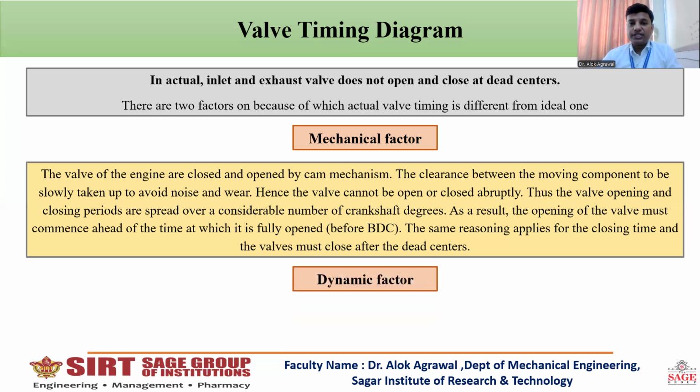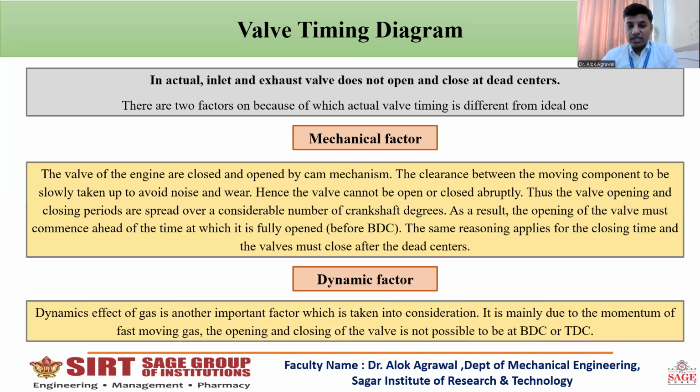Another factor is the dynamic factor. What is happening in the dynamic factor? It is because of the inertia of the gas. The effect of gas is a very important factor that needs to be considered, because when the gas is moving during the suction stroke, fresh charge is coming inside the cylinder. It has some momentum, some inertia.